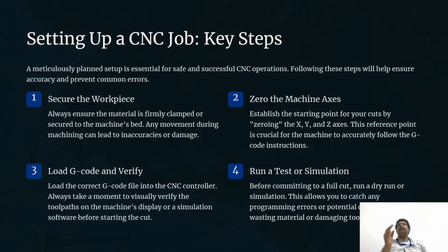Then we have to check if the coolant is on, coolant is off. Whether it is in metric or imperial. Whether the height setting is proper, whether the cutter number and the G43 offset are the same. So all these things have to be verified manually by us.